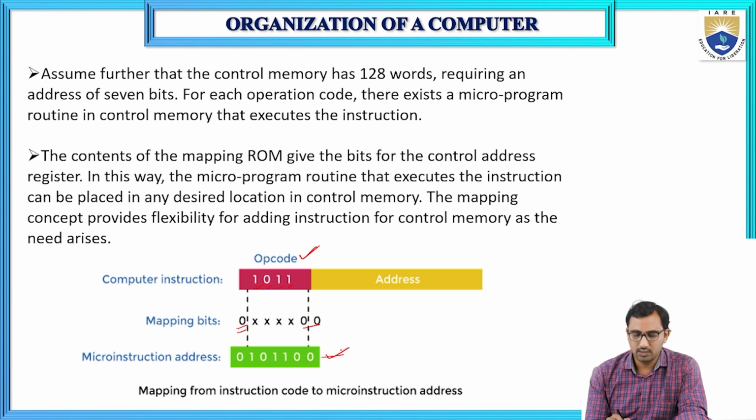Suppose 1011 specifies the operation increment. In order to perform the increment operation, we have to run the corresponding micro program. This is the address for the corresponding increment micro program, so the micro program related to the increment is located at this micro instruction address.